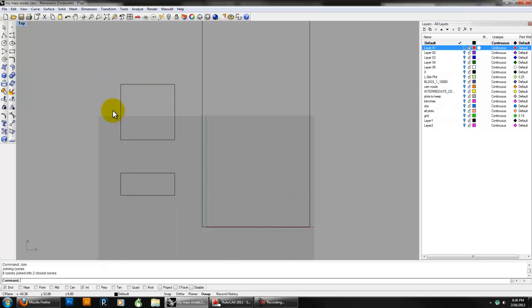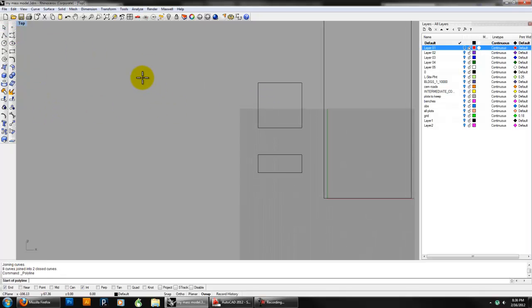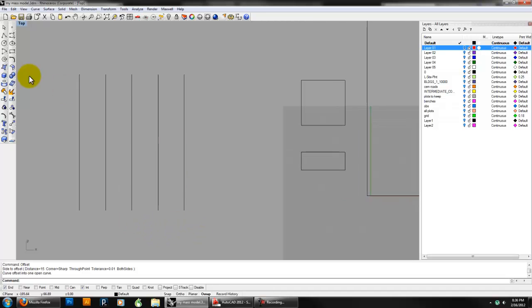So those kinds of techniques you can use, same kinds of things used in AutoCAD, or doing a series of regulating lines. So these are all going to be 15 foot. And again, I'm restarting the command by using the right mouse click. I think I talked about that last time. You can also use the enter key. And so I have a series of lines. Hold shift for orthogonal. Say offset. Distance D, 30 foot. And then using trim.